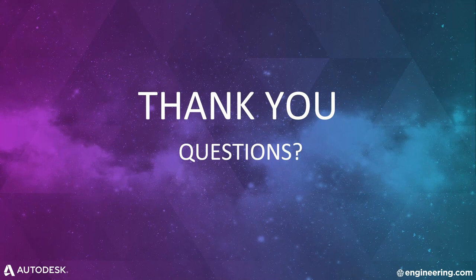Like in my specific case, we had 3-axis machines, we had 5-axis machines. I got really lazy and I really only wanted to do things on the 5-axis machines because it was so efficient. And those were the only machines in our shop that were really backed up the entire time because we wanted to put everything on them, even if it's not a fancy impeller, even something like a dice could go on a 5-axis. You could do 5 sides, flip it over, do the last side, and you're done. Or you have to do 6 different operations and movements in a regular vertical. So I hope that answers that question.